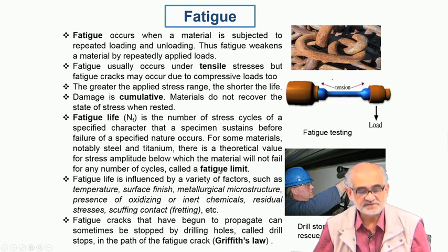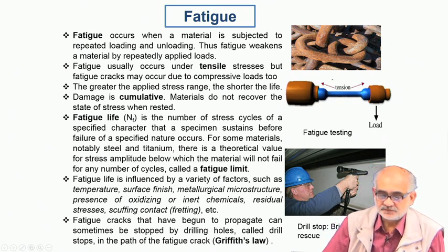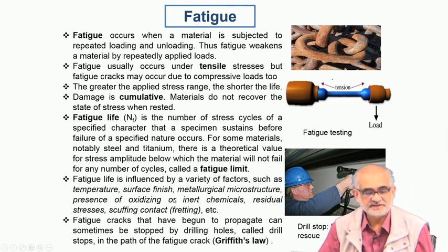But the situation in case of ceramics or non-metallic systems is not so simple. So you don't see an endurance limit curve which is flattening and becoming horizontal at the end, but the curve can actually continue to move downward. So there you have to apply a separate type of criteria for defining the fatigue limit. So this is important for a designer to understand what could be a fatigue limit.